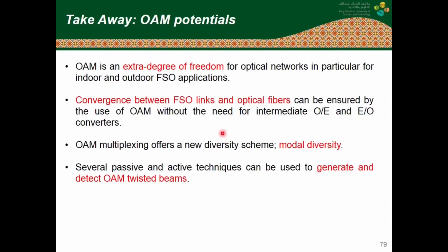So as takeaway messages for the potentials of OAM: OAM is an extra degree of freedom for optical networks, in particular for indoor and outdoor applications. Convergence between FSO channels and optical fibers can be ensured by the use of OAM beams without the need for intermediate optical to electrical or electrical to optical converters.